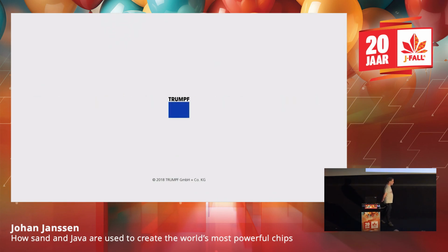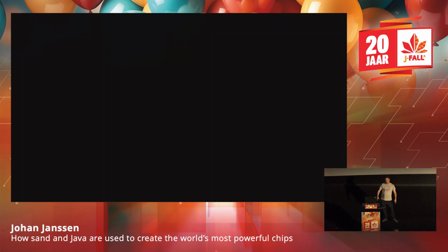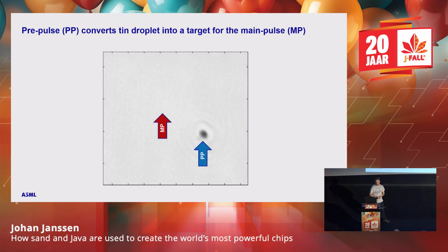Basically what you saw here is the wafer, and the laser, which is placed underneath the lithography machine in the basement. It's just as big, basically. It's a laser amplifier. It amplifies up to 40 kilowatts, and it's almost the strength some countries use to shoot planes out of the sky. It's one of the most powerful lasers, and they shoot at droplets of tin, as you saw in the animation. It hits the droplet of tin twice, once to make it a pancake, and the second time it hits it hard, and then plasma is emitted. And that happens 50,000 times without splattering the entire machine full of tin. I found it remarkable that they even managed to do this once, but it even runs in production, apparently.